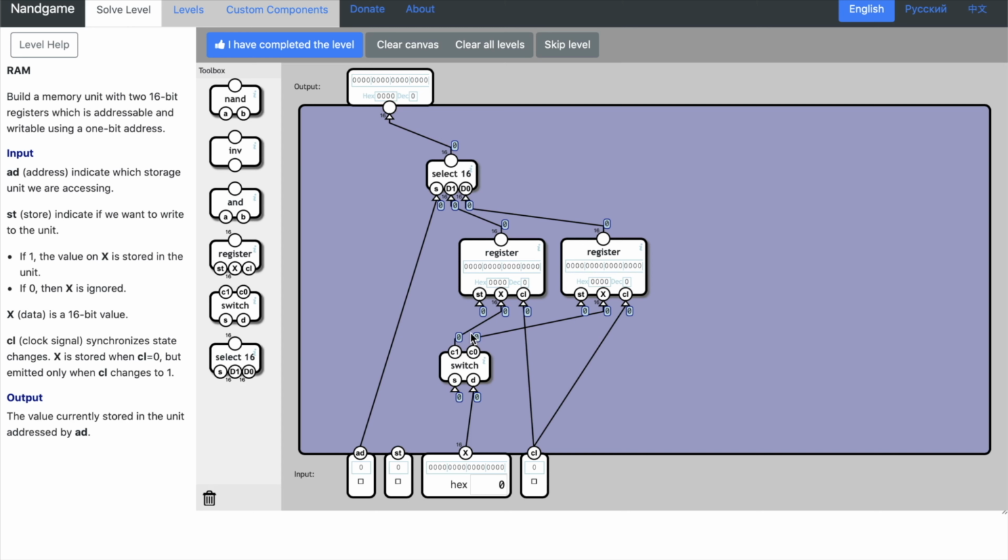Oh, I'm a dope. Okay, so we're going to break those. No, so if you remember, I said it was weird in the last exercise where we were always setting store to 1 and we were always just going to overwrite the value no matter what. Well, here we're going to do the exact opposite, actually. Right? We're always going to send X to these registers, but we're only going to make that register writable if the address has been selected, and the store flag is in fact the data payload for this demux.